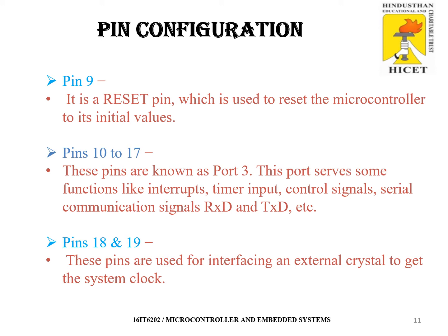Then one more time it will start executing the programs. That is what we call a reset. That means it comes back to the initial position and again starts the next execution cycle. For that purpose the reset pin can be used. If reset is high, it will reset the microcontroller. If reset is low, it will work accordingly.